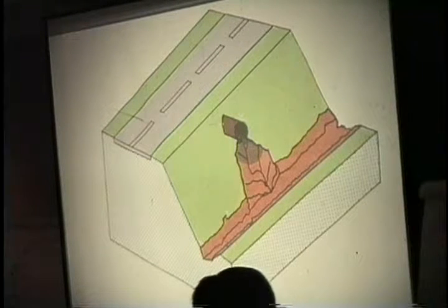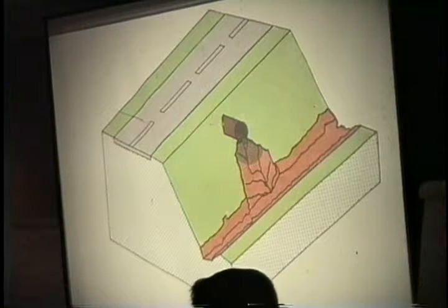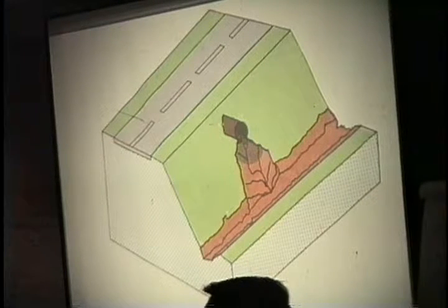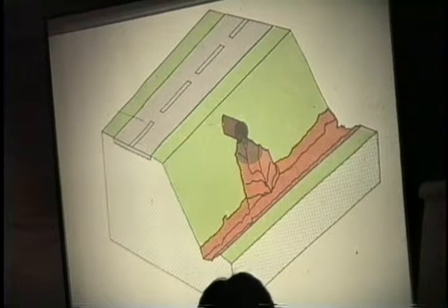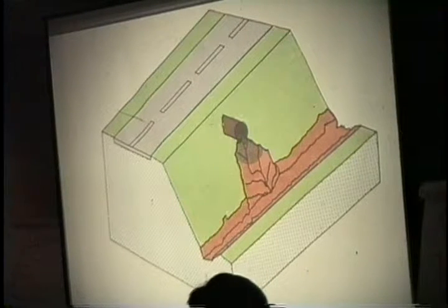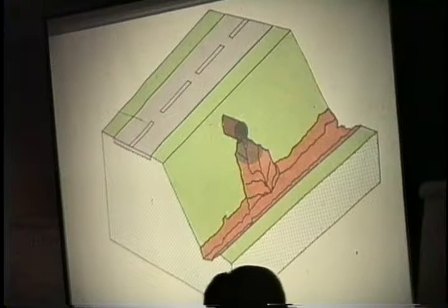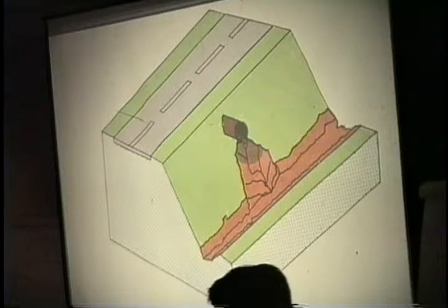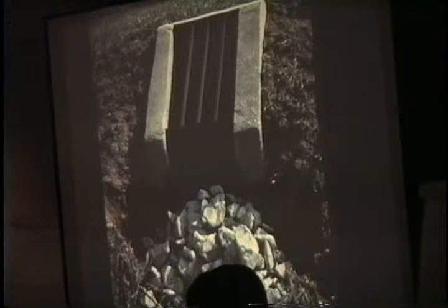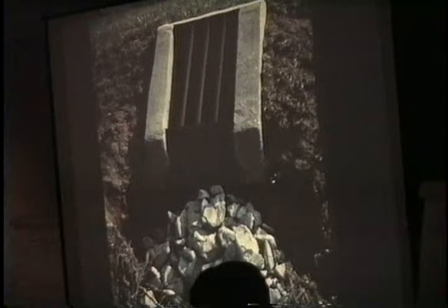As you steepen up the pipe, you increase tensile forces, and you might tend to pull the joints away. So this solution is not a good one unless the slope is very well protected, which you could do with fabric and riprap, and that might work very well. Here's an outlet, there's the riprap, but I still see erosion on the sides. It's a drivable head wall.